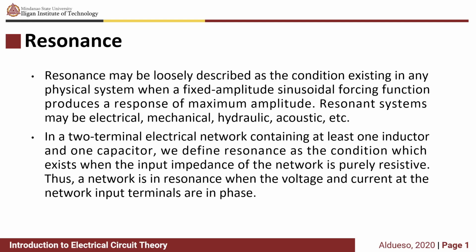In a two-terminal electrical network containing at least one inductor and one capacitor, we define resonance as the condition which exists when the input impedance of the network is purely resistive. Thus, a network is in resonance when the voltage and current at the network input terminals are in phase.